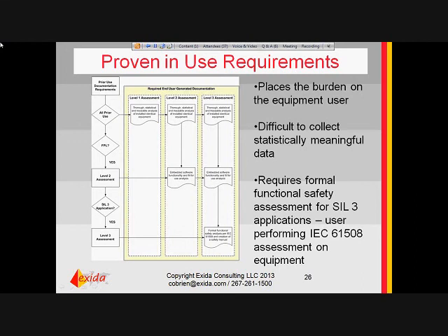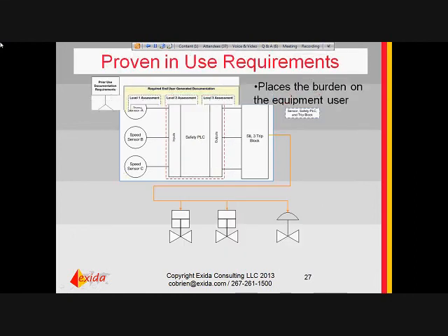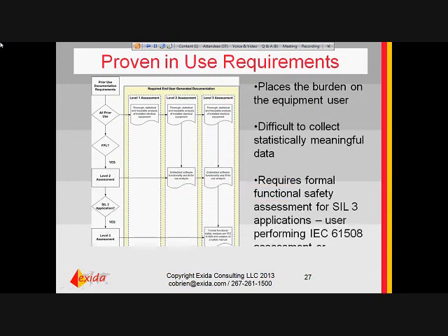Are you configuring the PLC, or is this, are you using a safety-rated PLC for the software, or is it embedded software? No, with the PLC that wouldn't work because there are more functions or mathematical functions which you cannot program in a PLC. So it's a question if you would use an FPGA or. Okay. But so still, you would need to, let's say, get an assessment per 61508.